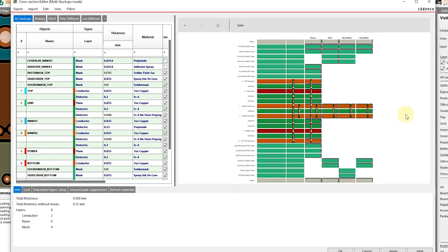So all of those things will have to be ironed out along with your via specifications as well, right, whether you need any laser drilling or your end-to-end through holes are sufficient for your purposes or not. So we'll do a deeper dive in a future session on that topic. But in terms of actually setting up the stack up, this is how and where it will be done.